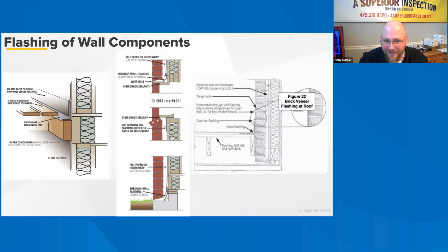If they want to negotiate that, obviously that's their prerogative. But if they're not willing to do anything, then I just recommend that they go yearly and check the sealant at all of those penetrations and continually maintain that sealant to ensure water intrusion does not get back behind them.